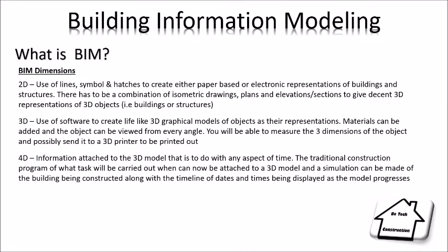4D, what is 4D? So it's information attached to the 3D model that has anything to do with any aspect of time. So if I'm looking through a 3D model and I click on a smoke detector and I'm given some information about when that smoke detector is planned to be installed, because we're in the delivery phase, we're designing, and I'm given some information about the date that smoke detector is to be installed, that would be considered